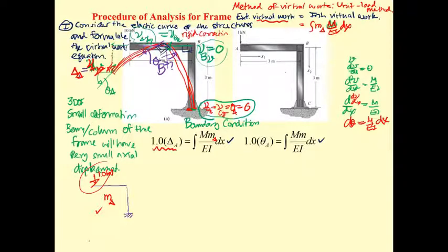And then if you determine the slope, you get the same thing, but this time your frame is subjected to its slope. Slope is the rotation. So to produce the work, you put the 1.0 kilonewton meter to this, and this 1.0 times this theta sub A is going to produce the external virtual work. And again, this is going to produce m sub theta, and this m sub theta again produces the internal virtual work. So this is equal to the integral of m sub theta.